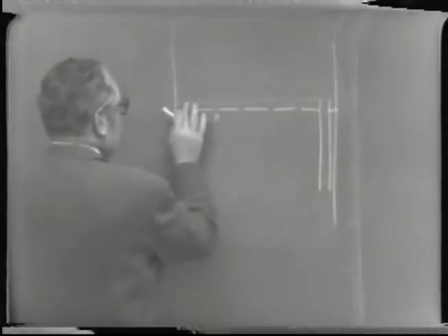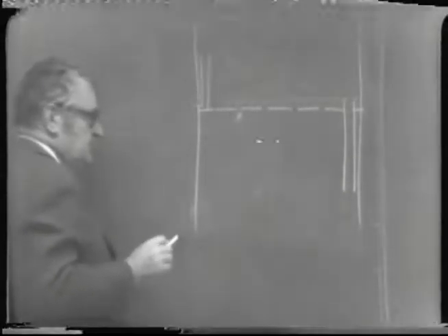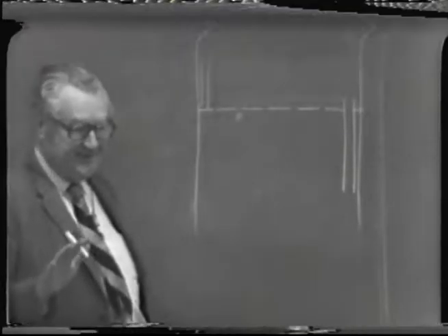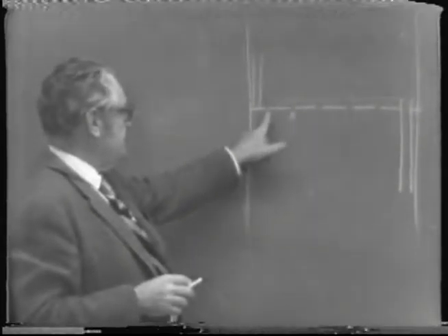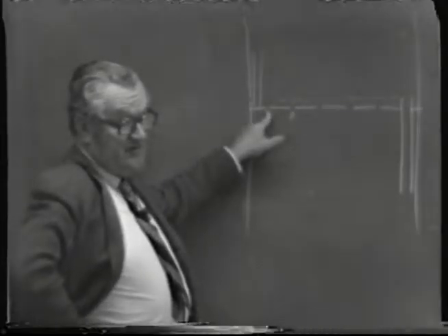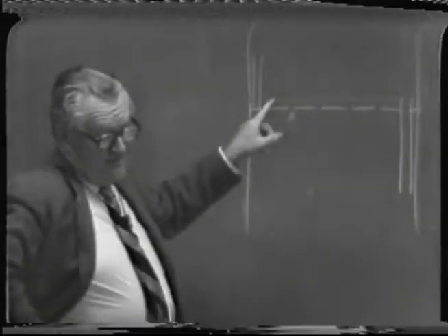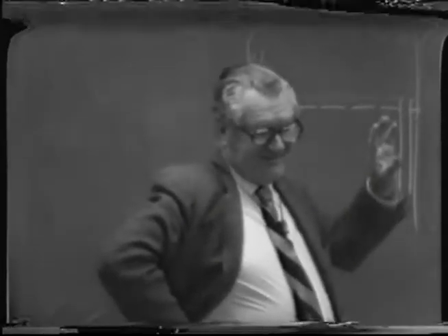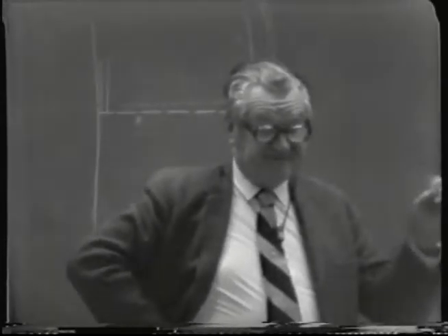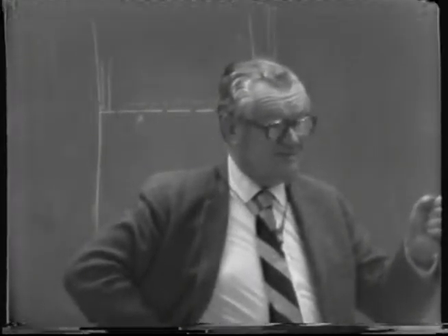But the smaller the holes that you can have, the more flexible an arrangement you have. Sometimes they've been made as small as a 1/4 inch diameter, but that small a hole will not really satisfy the requirements in the alcohol industries very well, where you have particles that may plug the holes at that small size.